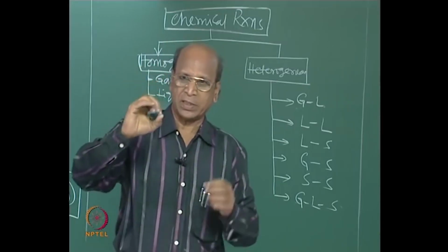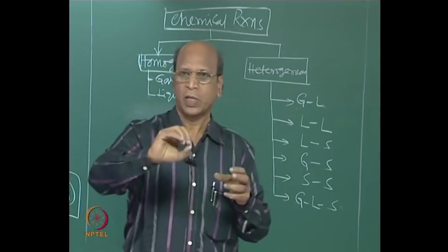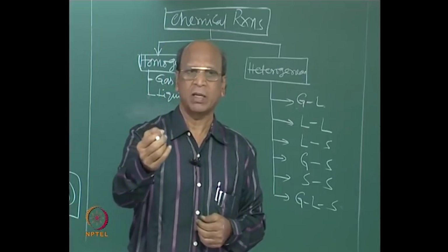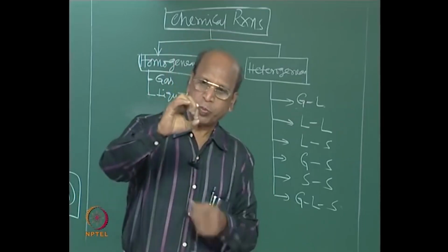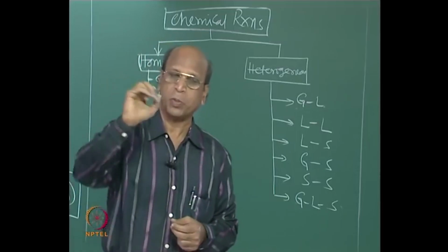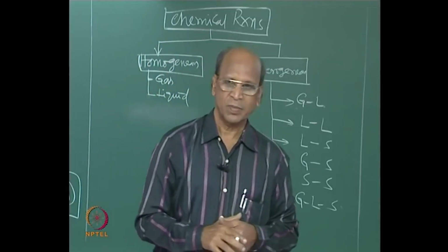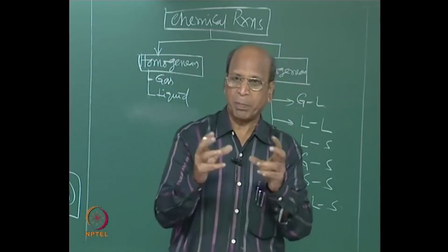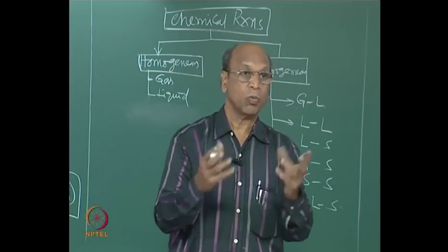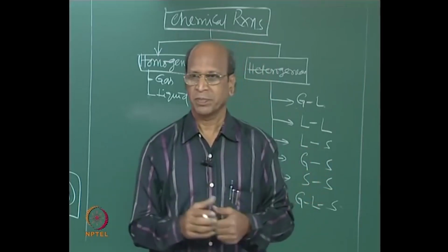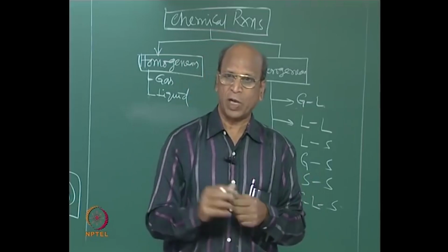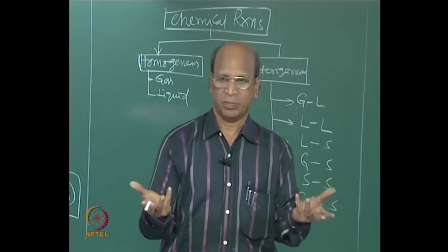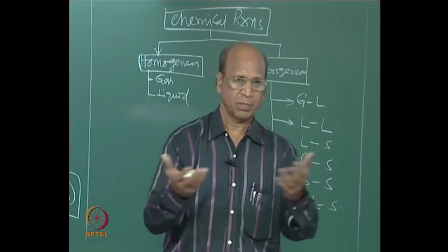That heat exchanger type means it is like heat exchanger where inside you have tubes, inside the tubes you have the packed beds, and those tubes are not normally more than 2 inches. When you have tube diameter itself 2 inches, what should be the particle size? It may be 1/4 inch. Otherwise, if you use again big particles, you have what are called wall effects. You heard of wall effects. Okay? So, wall effects means when you have large particle and small diameter, your flow will not be uniform. So, that is why we say that it is wall effects and all that.